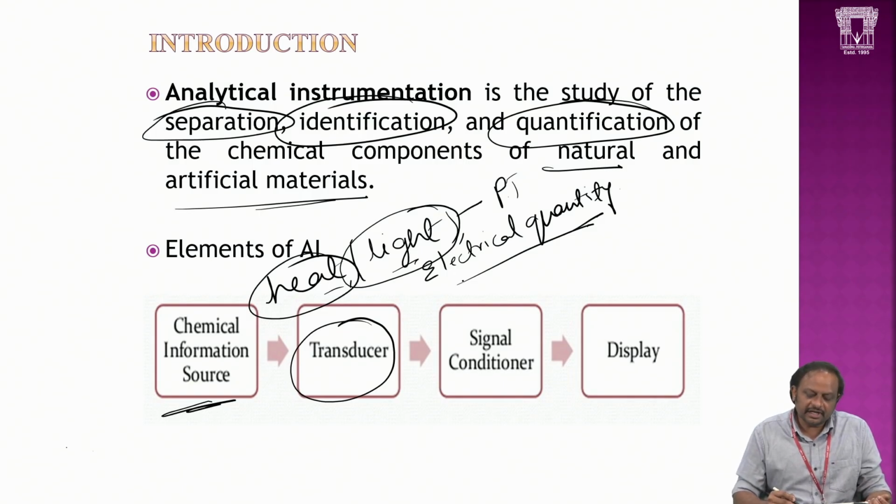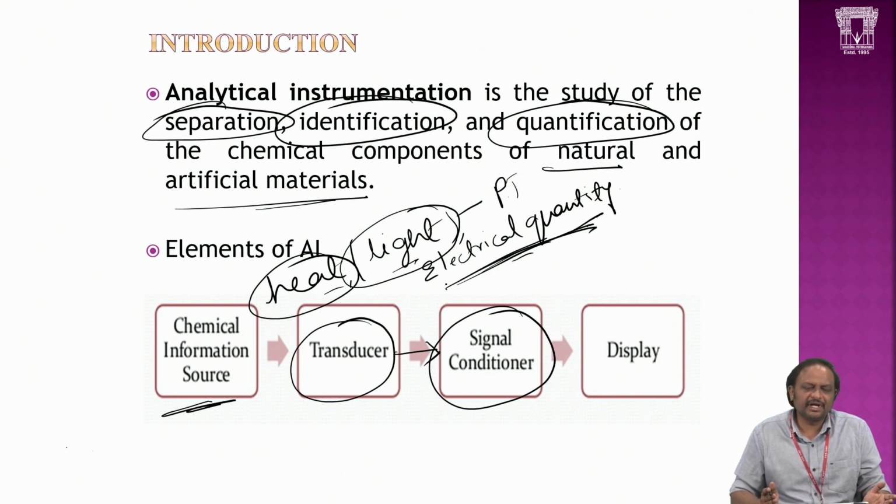Or suppose your chemical is liberating an electrical quantity, so you rely on the usual transducers, that is voltage transducers, and so on. Usually electrical quantity is the output of any transducer, because the definition of a transducer is converting one form of energy to another form. So you take that electrical quantity and apply proper signal conditioning here, because the electrical quantity has numerous spurious noise signals, as the environment also has a lot of noise signals, right?